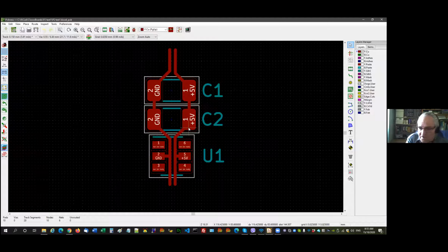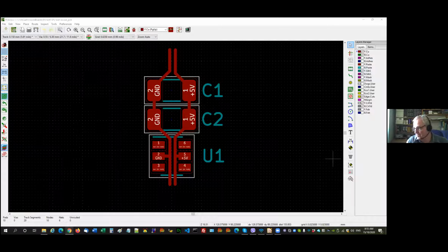Now, my P1 design, I regularly clock it at 104 megahertz. But I've got specific bypass. I can't do that with a normal Prop 1 board. And that tells me that I've got it right. So down here, come into the 5 volt, see how I've brought the ground in. So that's it. Now, if you want to go to a little bit more about that, I'll flip to another screen.